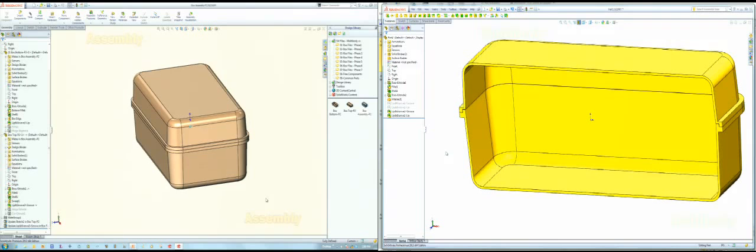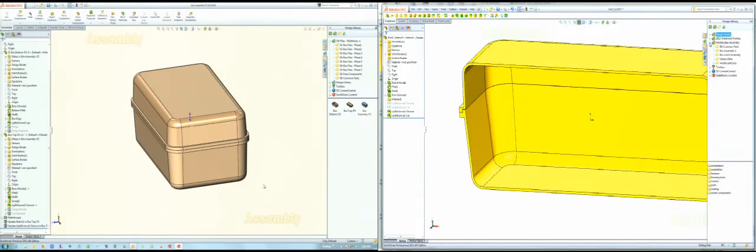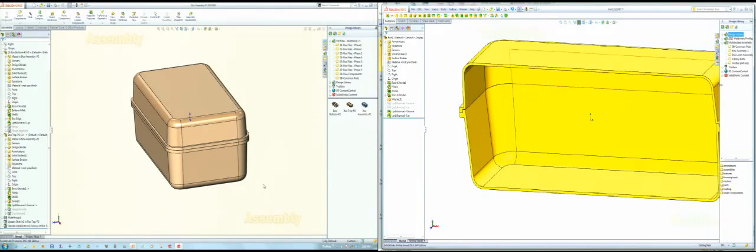Okay, the next thing we have to tackle is putting a hinge on this. As one of the earlier questions indicated, about why we didn't link the shells together, the hinge is kind of the same thing. We know the circuit board is only going to be within a certain size range. We don't know exactly how big it is, but it's not going to go from this big to this big. It's going to go from this big to this big or this big, so it's going to stay relatively small. So the hinge we create is going to be the same size no matter how wide or long the box gets. But we have to account for the fact that the box may get wider, which is going to push the hinge further back from the origin.